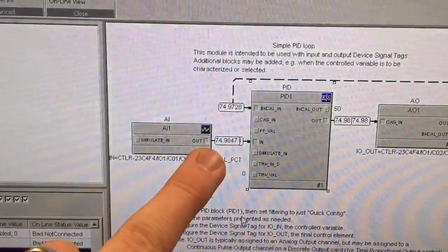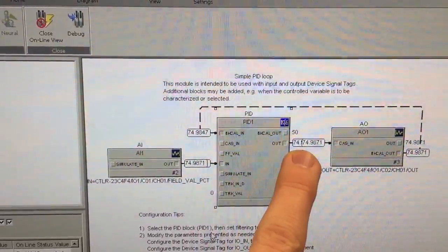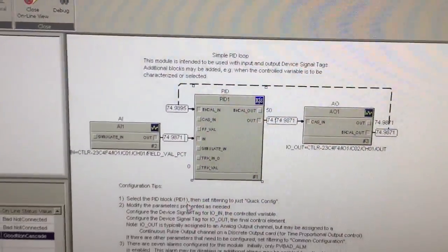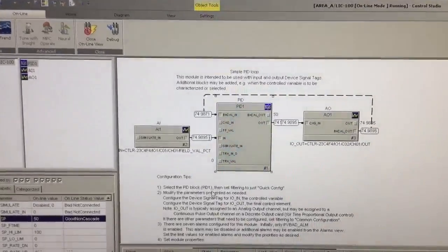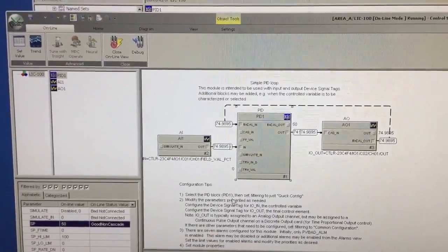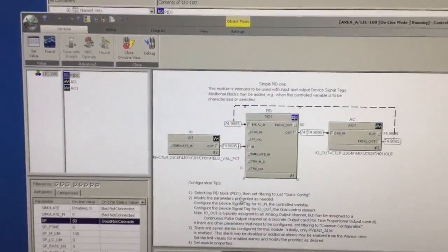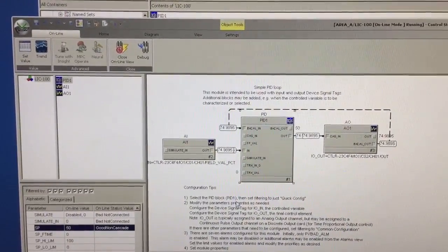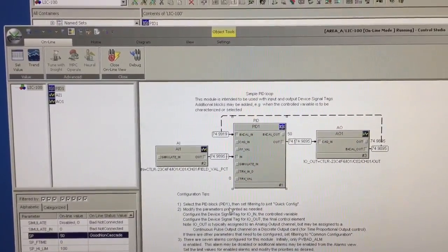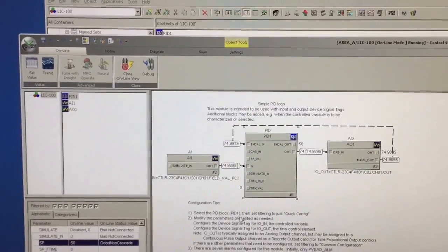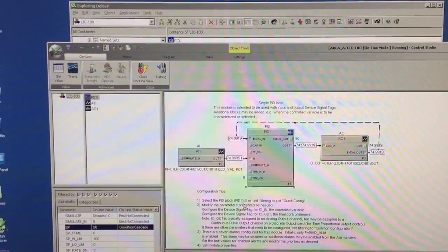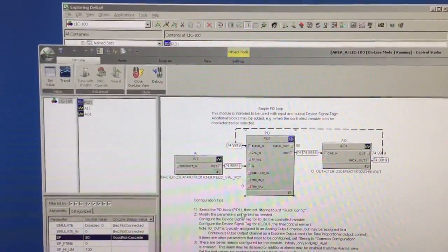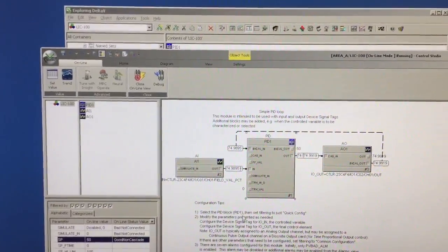This went to 75, and so did our controller output. So we verified the operation of this calculation by using that controller output calculation and applying it here in this DeltaV control system. There are many other things that you can do with this block, and I just wanted to demonstrate the very simple controller output calculation used here in DeltaV.